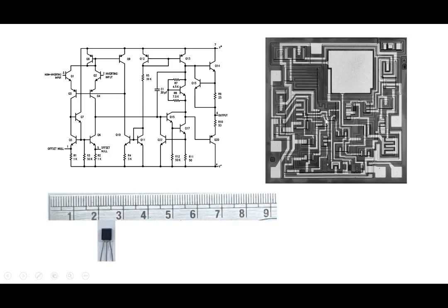Now after that, you can package it, and the package is not going to be larger because the silicon piece is still very small, right? So this is the size that we showed of a single transistor, and if you took a circuit of 20 transistors and 10 resistors and a capacitor and put it in a package, this size is still very small. You can see the package size is less than a centimeter still. So the invention of the integrated circuits made it possible to build very complex circuits consisting of lots of transistors, and still the size remains very, very small.